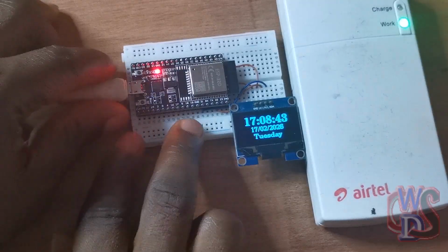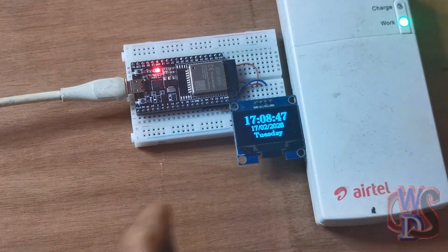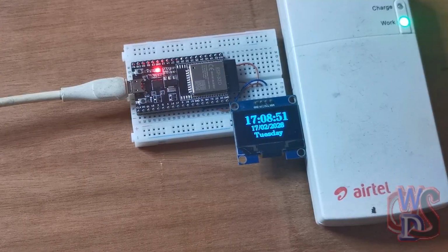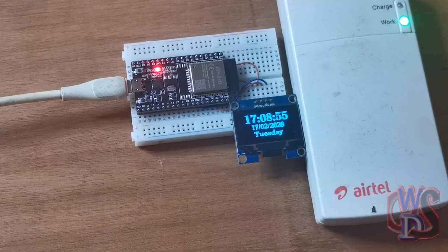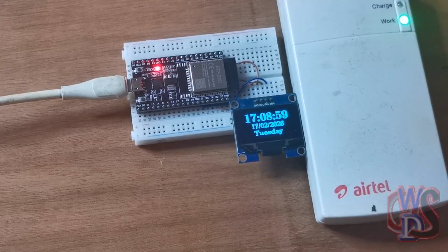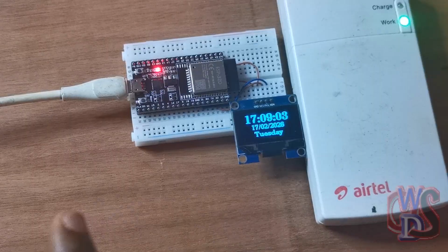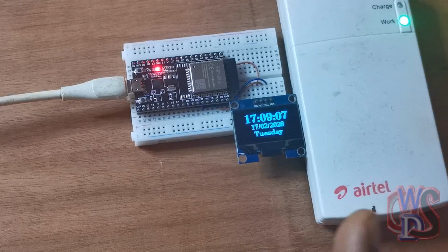If I unplug it, if it were an RTC module, the moment you unplug and plug it back, it's going to start from that same time that you turned it off, and it will start counting again, except you decide to program in such a way that you add an external CMOS battery that can hold that time in place. Thereby, whenever the system goes off, that RTC module is not turned off at any point in time.